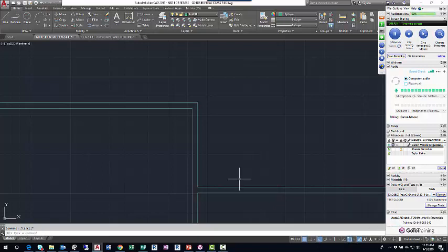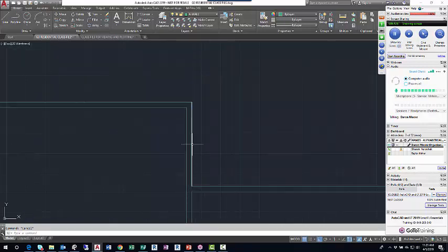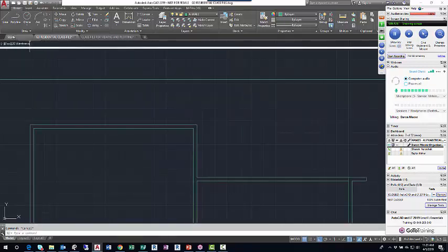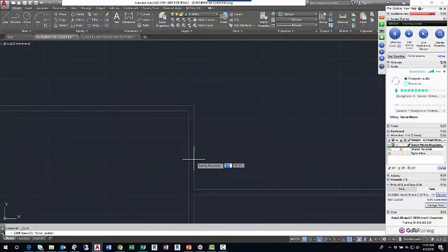And with the midpoint object snap, if this wall line is all nice and trimmed out, I can go line, find the midpoint, so that when you see that triangle, that's the midpoint. I'll left click that, and I'll just move towards the left and left click. So that line is right in the middle of where that opening will be. Got it. Thank you. Yeah, sure, no problem. And I'll just do an offset of 1'6", and I'll offset it up and offset it down.